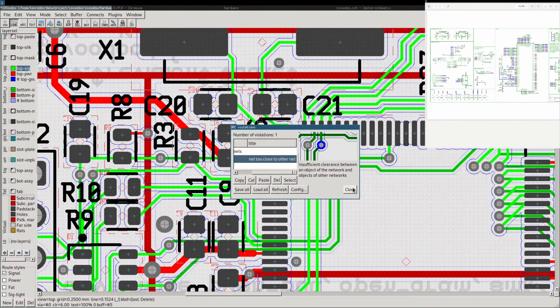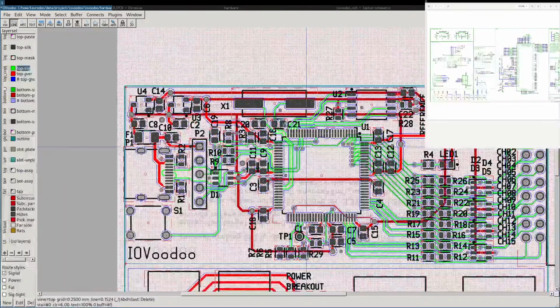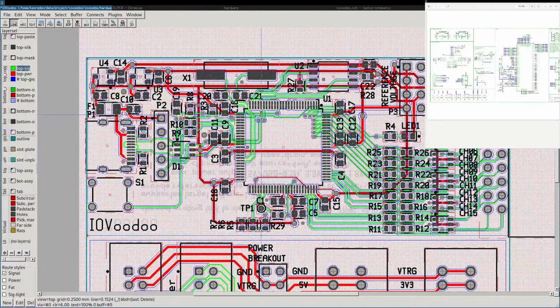But I should create a DRC rule and write a DRC rule for that. For now, let's leave it open. All the DRC is passing, meaning this board is okay. And this is after routing, so you check all is routed and then it respects the DRC. But we are not complete.